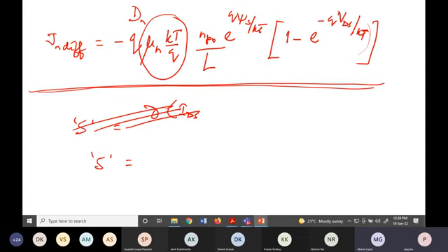Yes, sir. Okay. So from this Jn diffusion, you can find out the corresponding subthreshold current, because from the current density you can find out current. All I am aiming at is that this part will be close to 0, and it will depend on exponential q psi s over kT.